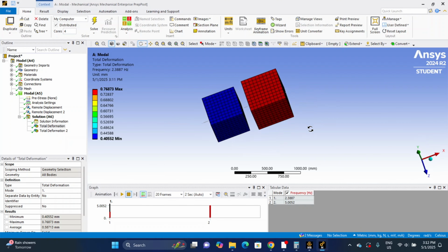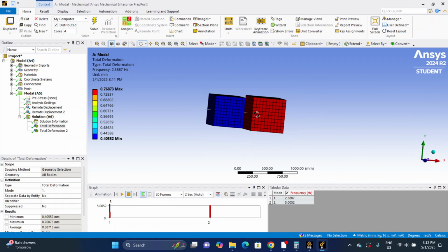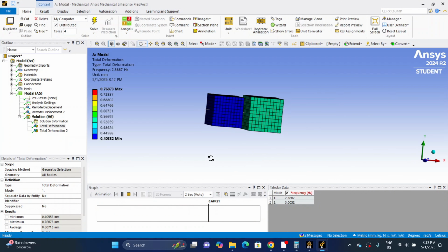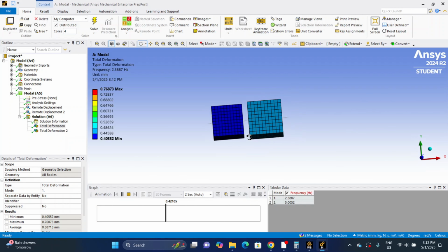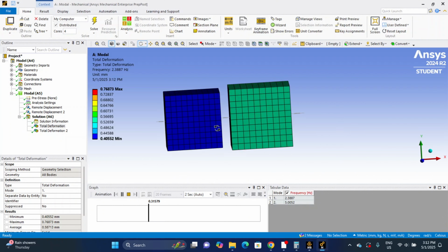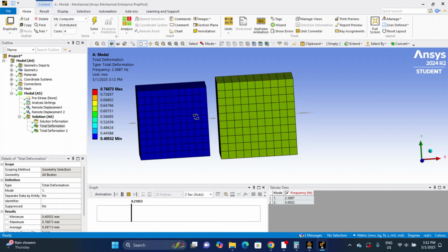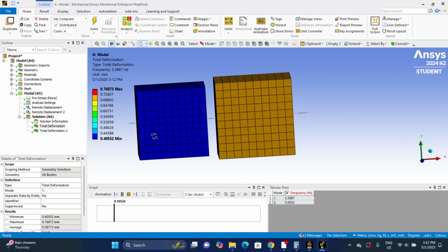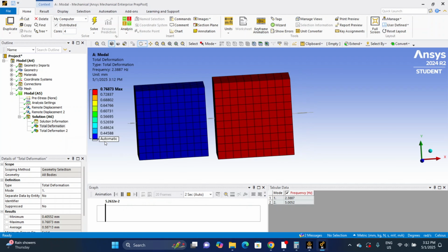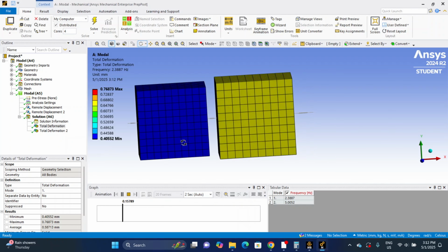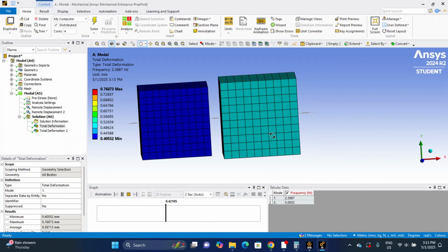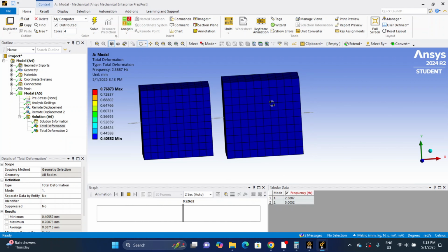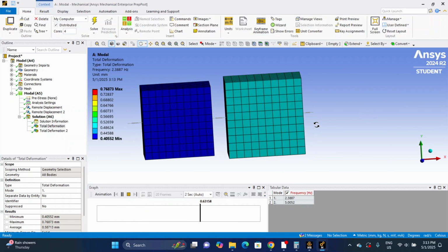So this is the mode shape for the natural frequency of 2.3887 Hz for the first design, and let's see the animation. You can see when the mass 1 is moving at 0.40552, the mass 2 is moving at 0.76873, and they move in the same direction.